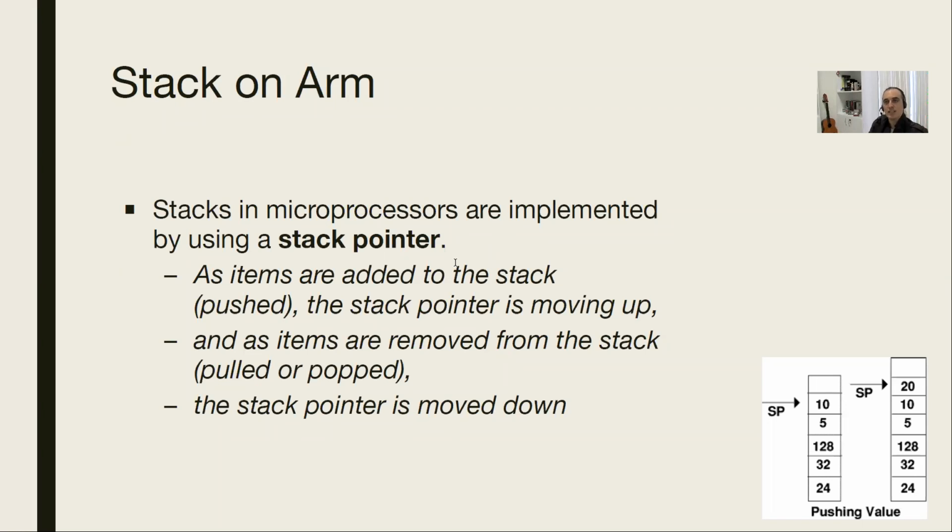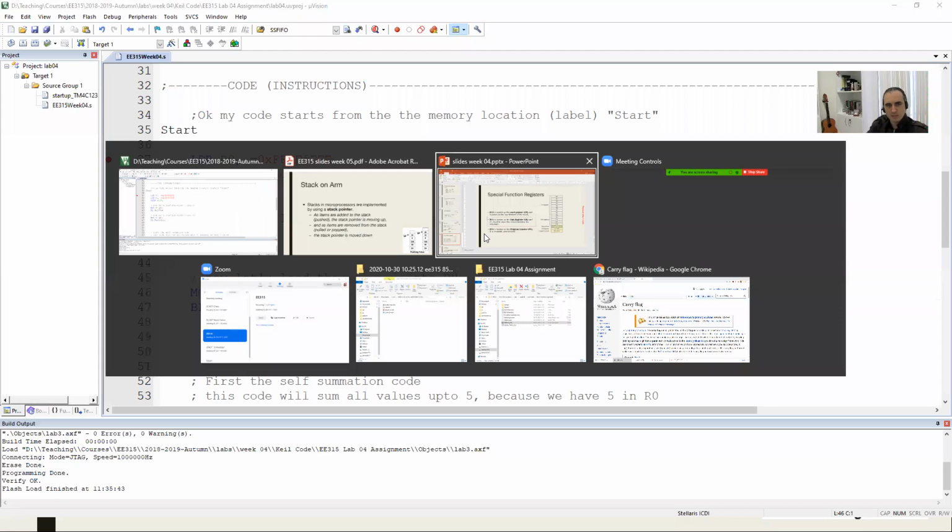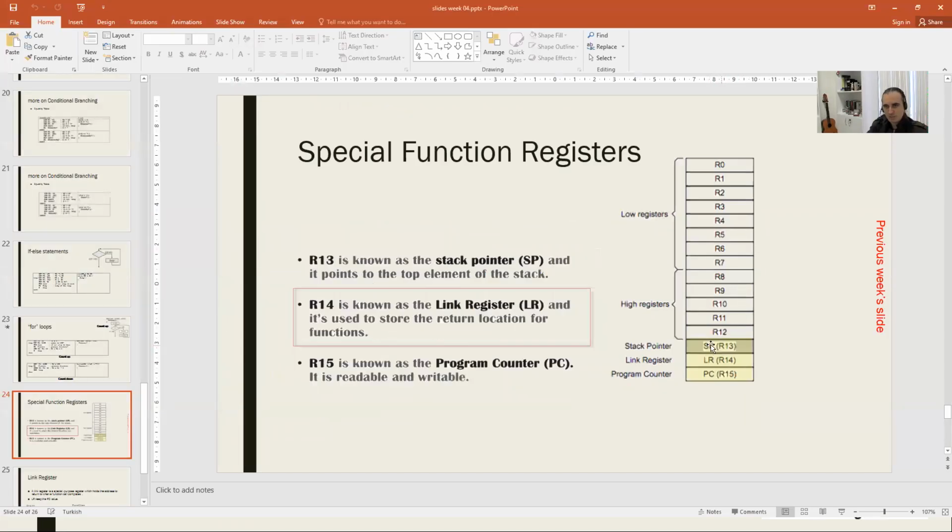So actually, you do have a stack system in your hardware you can readily use. How come? Well, it's implemented by something called the stack pointer. Do you remember the stack pointer, SP, from the other slides? Yeah, SP. The stack pointer shows the last inserted element's address location in the memory.